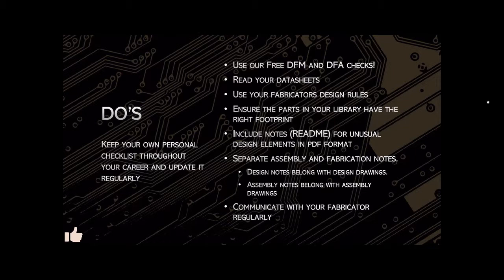And then the next one is to read your data sheets. Also, use your fabricator's design rules. So if you've been using your fabricator for a really long time and you understand their rules, great, or if you don't, I would get in contact with someone and go over the design rules that you need. That way you have them handy when you're actually doing new designs.